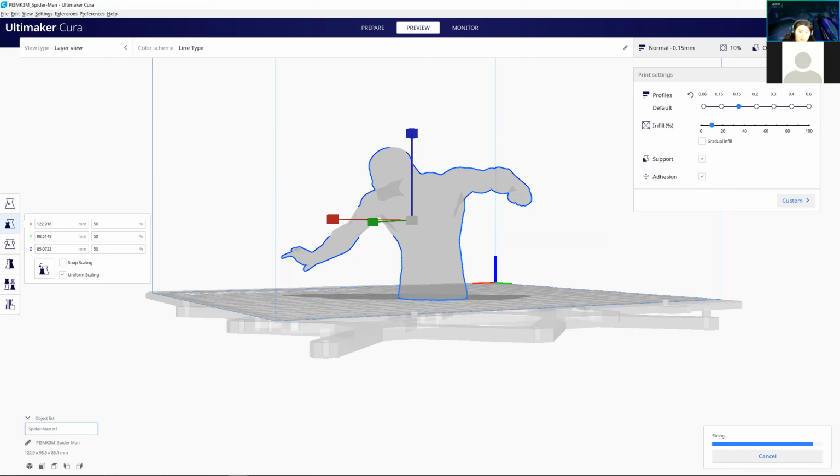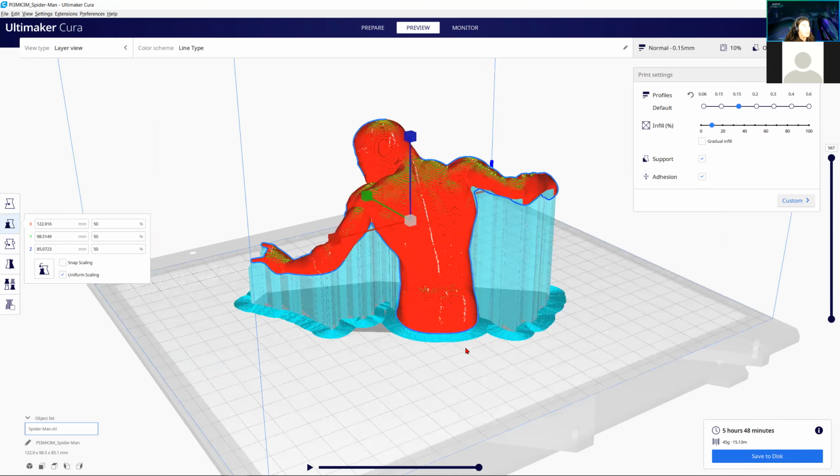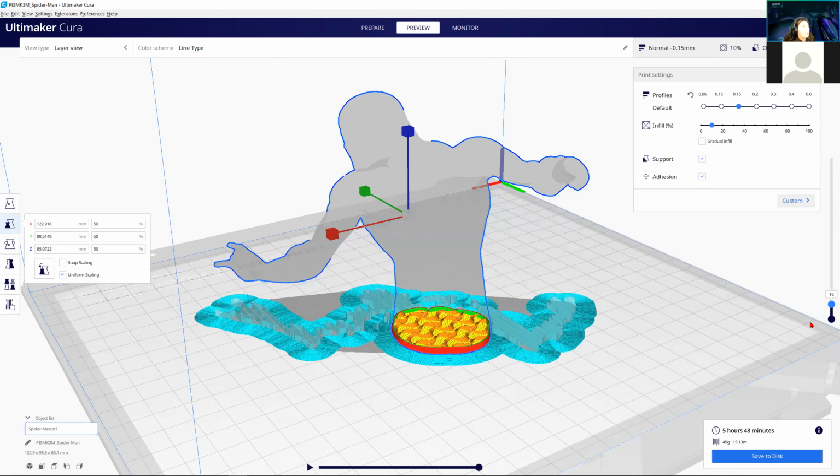So how does one remove adhesion and support with knives and blades? Let's see if I have one of the parts with me right now. It's usually a scraper tool. The one I prefer to use is like a spatula, like if you were using it for cooking. You get underneath the adhesion, and for this it's really easy because it's only one layer. This would be the very bottom layer, and you can see it generates the toolpath for that. Since this is one layer, it's really easy to scoop under it and take it off. And for support with knives and blades, actually, I think I have something printed where I have to remove some of the supports, so I'll show you guys how to do that at the end of the video.